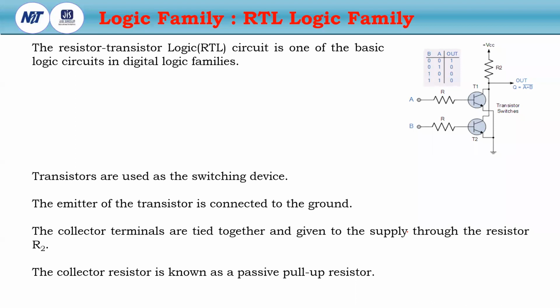In the RTL logic family, the basic components are the resistors and the transistors. It is a bipolar saturated device where the collectors of the two transistors are connected with the driver resistance, that is with VCC.